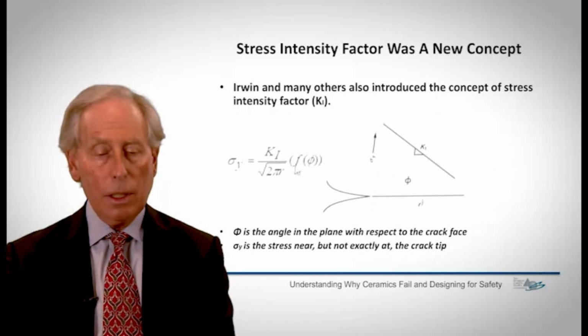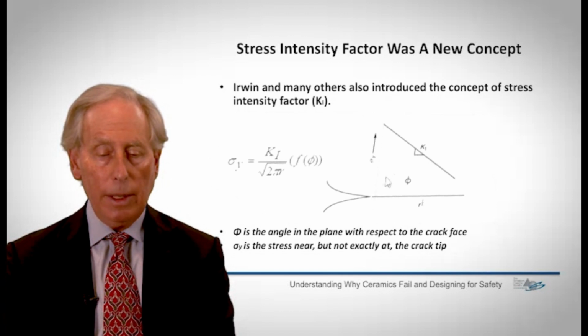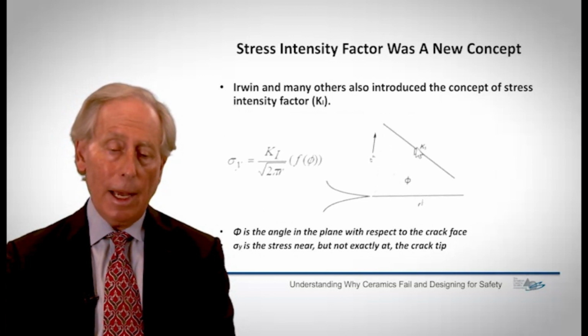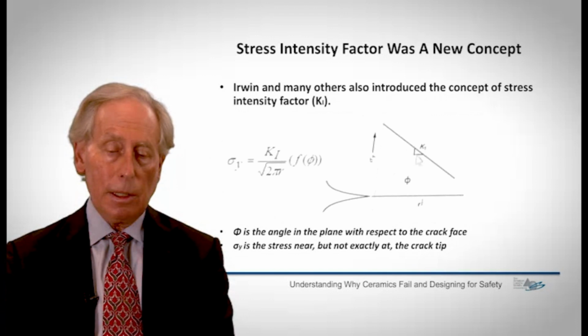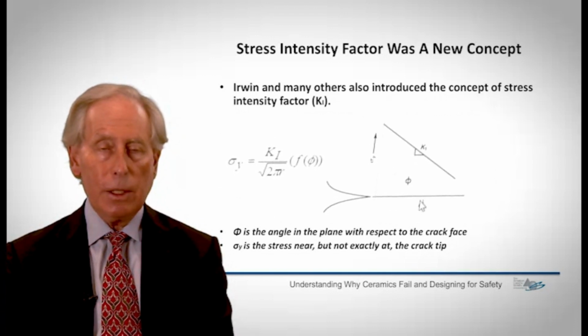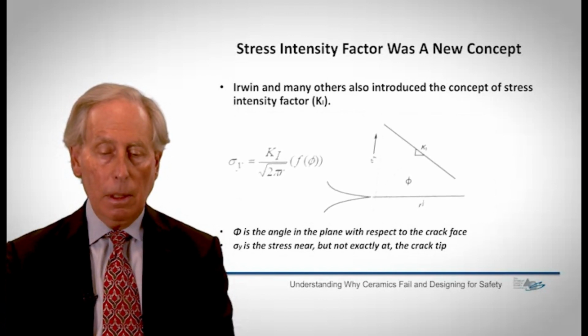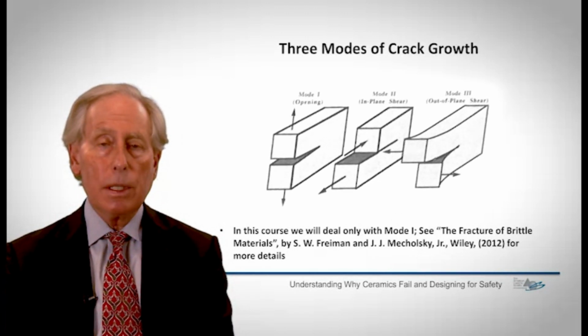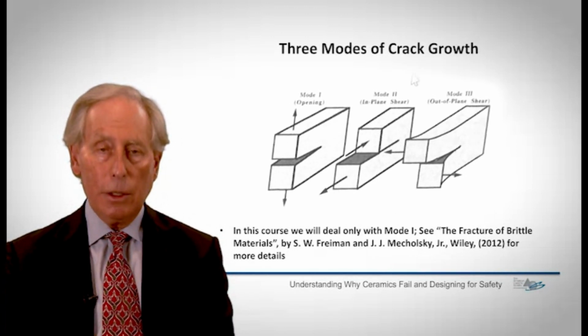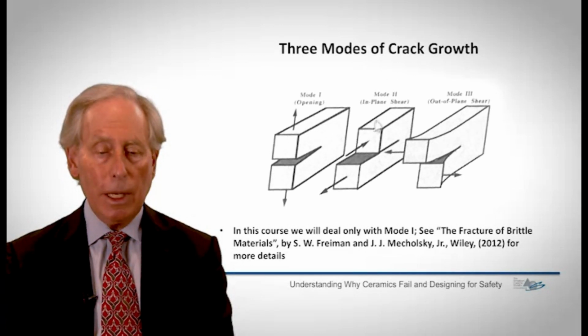It also decreases into the plane of the screen that you see, but we won't go into that. There are a lot of details involved in here. Fracture mechanics is a very complex subject, but the idea of defining stress intensity factor is really the slope of a curve of the crack tip stress as a function of distance away from the crack tip itself. And there are actually 3 modes in which I can apply the stress, and there's a stress intensity factor associated with each of these modes.